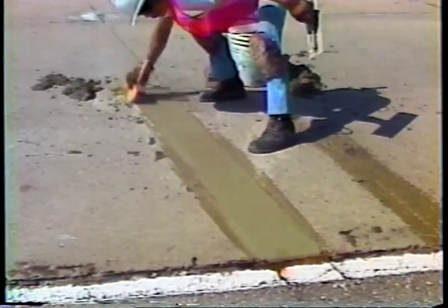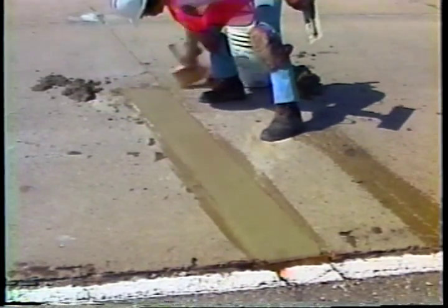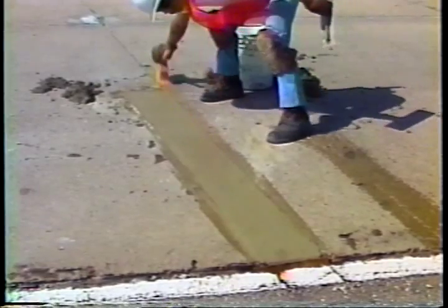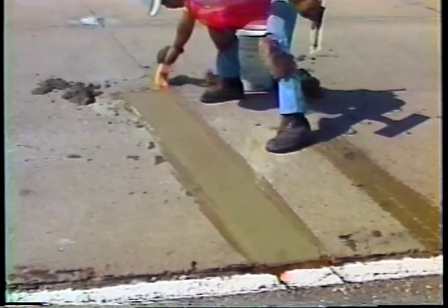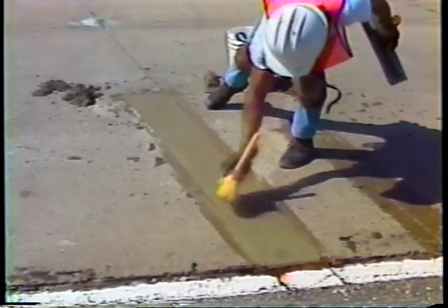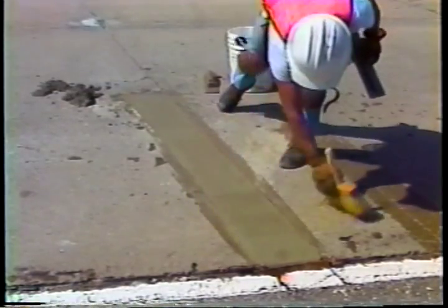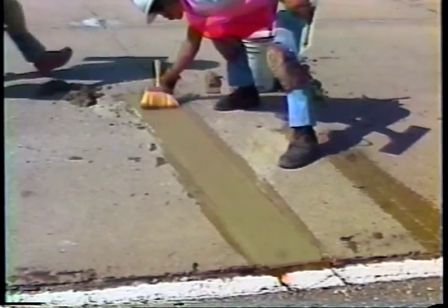Although partial depth repairs are usually small and have no significant impact on friction, texturing is recommended to make the repair surface similar to that of the surrounding pavement. After finishing, it's strongly recommended that the edges of the repair be sealed. This can prevent delamination resulting from water seeping at the edges. A 1-to-1 cement water grout provides an excellent moisture seal.